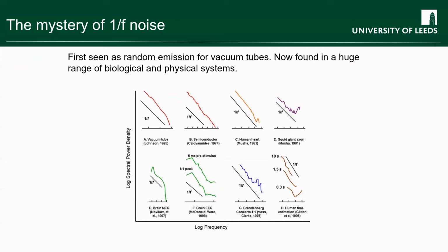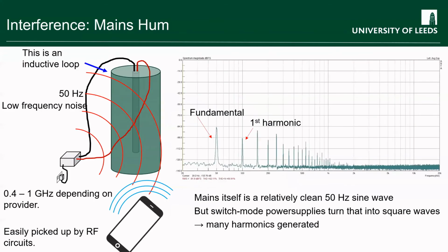So it's a really ubiquitous source, and unfortunately nobody really understands why all of these different ways you can generate noise all end up giving you a 1/f source. I mean, there are various esoteric theories put forward involving string theory, but realistically nobody actually understands the origin of 1/f noise. It is just something that we observe in systems. Okay, so those are three different types of intrinsic noise.